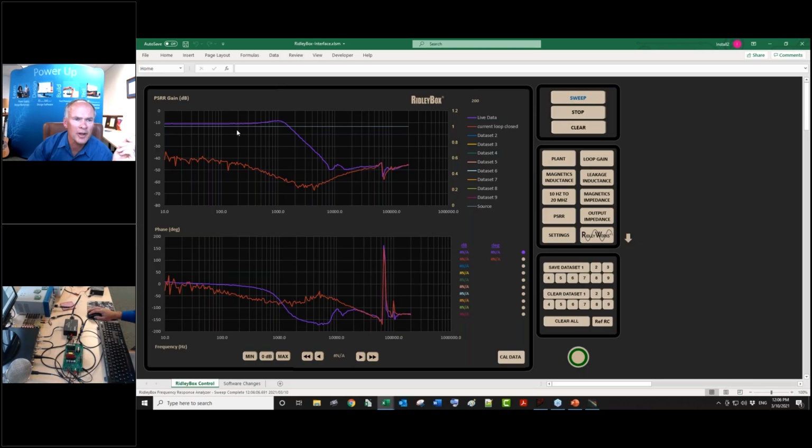Okay, so this is what you buy with current mode. So when people don't want to do current mode, it's like, okay, just work a little harder because this is nice to have. At the line frequency, you're just down in the mud at this point. Yeah, somebody else, by open loop, I mean a very slow voltage loop, like a 1 hertz, a 0.5 hertz voltage loop. So that's what that one is. So from 10 hertz on up, there's no loop in there.